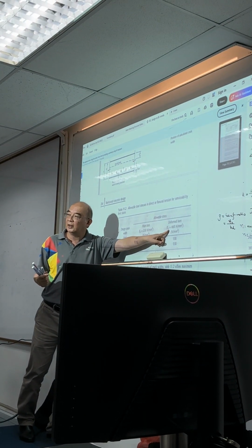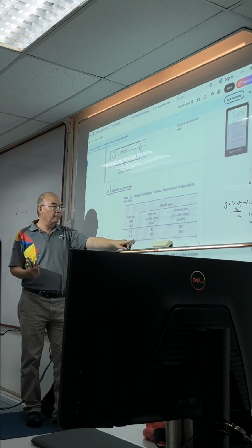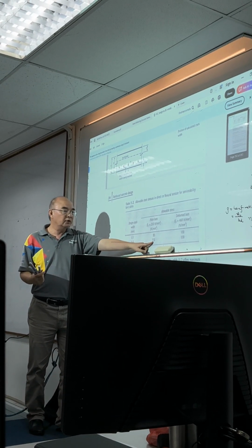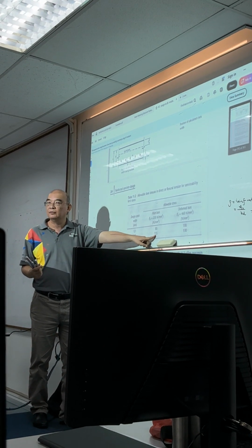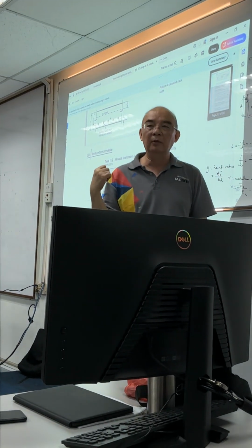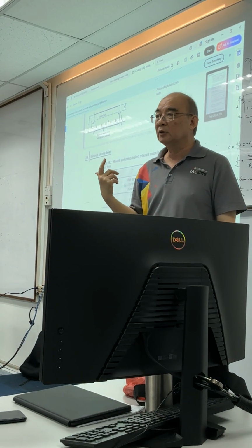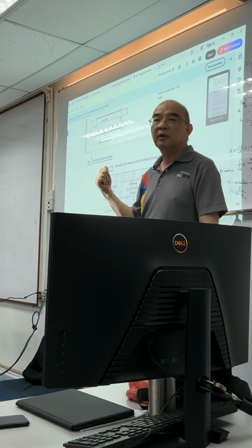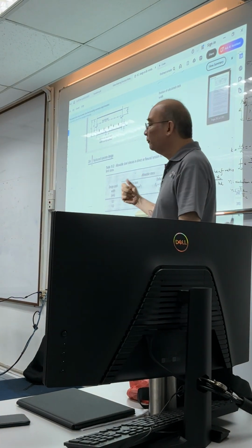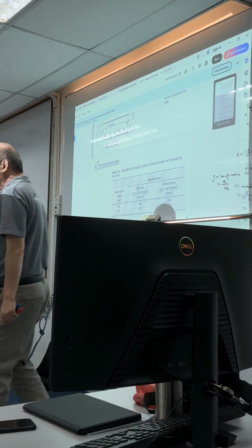Deformed steel, which is high tensile, has Fy equal to 460. And this 0.2 is 115. Just now we have 144, the calculated stress. That means clearly it has exceeded the allowable stress.